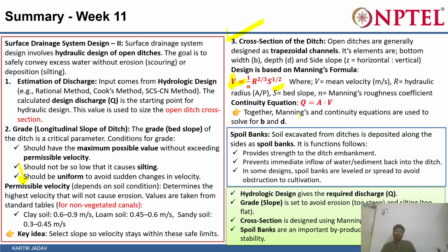Then you have a continuity equation. So together the Manning equation and continuity equation are used to solve for B and D, right? Your B is the bed bottom width, and D is the depth of your channel. So this will help us to design this drainage.